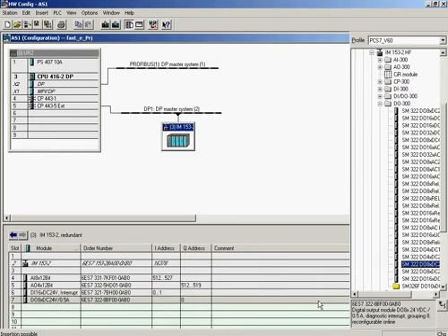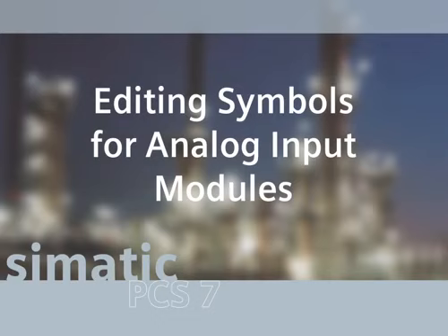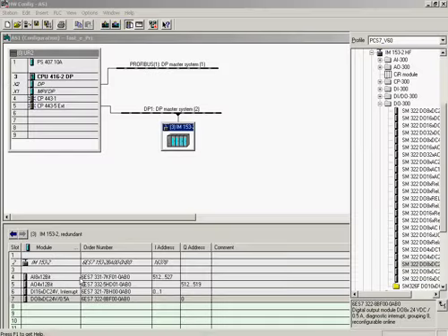In the hardware configuration, the IM153-2 interface for the ET200M distributed I/O system was inserted into the rack and communication was set up. The ET200M rack was expanded with analog and digital input-output modules based on the hardware that is to be used on the project. In order to use symbolic addressing of I/O throughout the configuration, instead of rack slot channel numbers or memory locations, each address is given a unique symbolical name and comment in the Edit Symbols dialog.